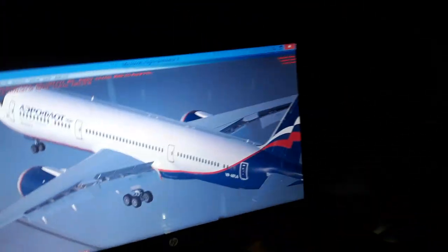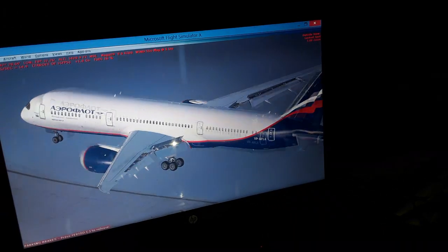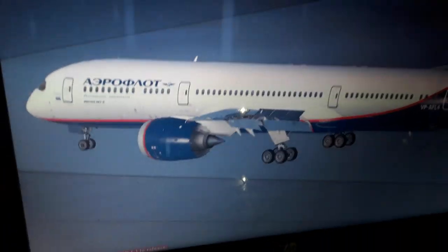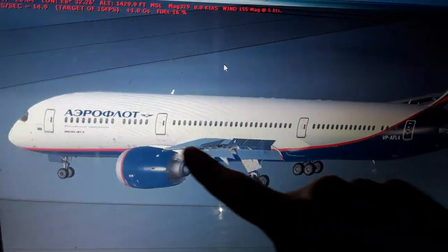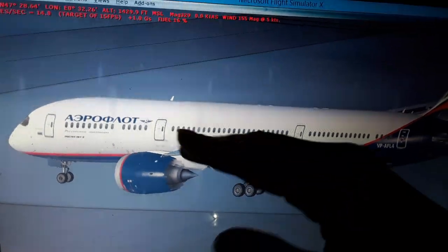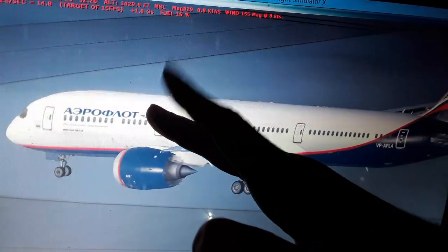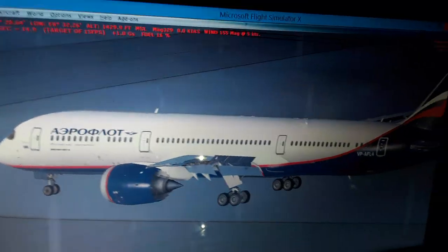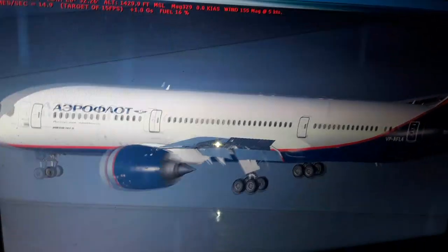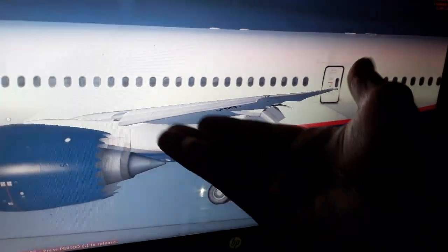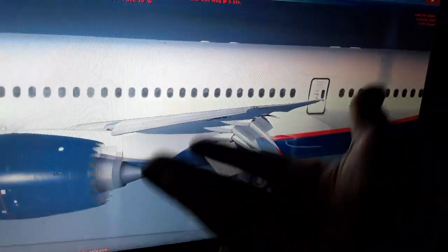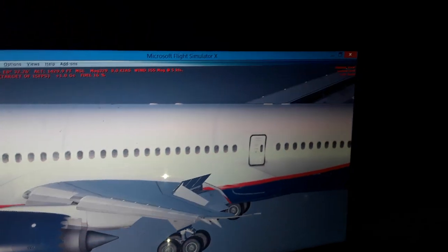You can see also the wings here, using Bernoulli's principle. The bottom surface of the wings is more flat, so the airflow uses Bernoulli's principle, and we have the curvature from the flaps extended. Also, we're going to have an angle of attack like this in flight, maybe. So the airflow is going to be moving much lower below the wings. So this is going to give us higher pressure. It's going to push the aircraft wings up into the air with the weight of the aircraft.